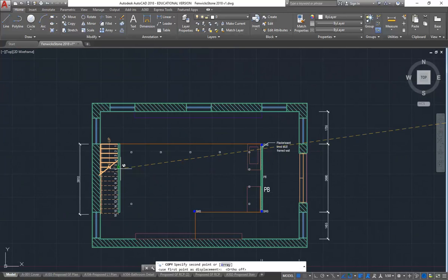Okay, so even though it may not be required to have a smoke alarm that's on this level, I think I'm going to put one in anyway, just to be safe. And there are a few different locations actually, because you've got to remember this is a void. So when there's a fire, smoke would rise up around these, the two sides of the ceiling or the floor structure. So it really could be anywhere, but you probably don't want it too close to the kitchen, because it might go off when you don't want it to.